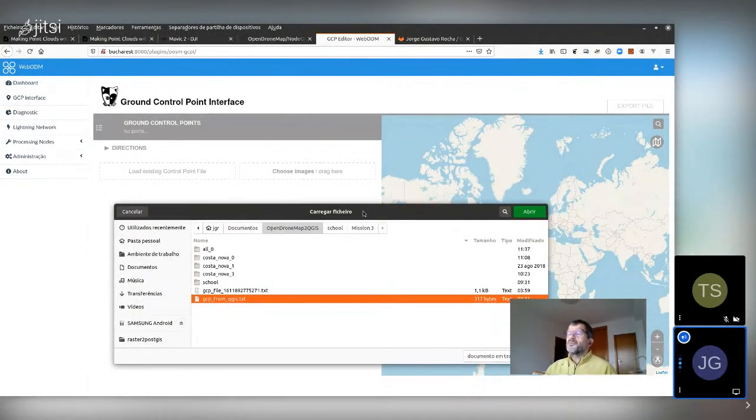So I was discussing the ground control points and how you can use them here. Basically the workflow is, before you fly, use ground control markers. You can use any kind of markers, but my humble suggestion is to use matte tiles of 2 different colors, put 4 tiles in each place, and then use some GPS to survey the points. If you want to do it properly, you have to take some time and stay there for a couple of minutes.